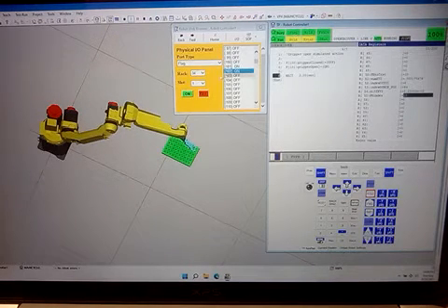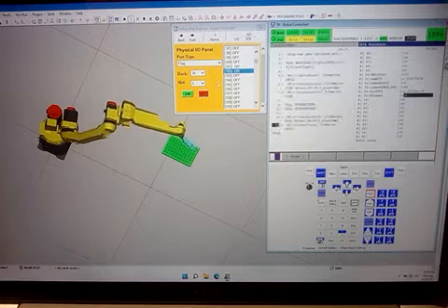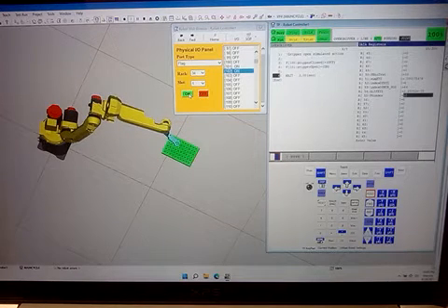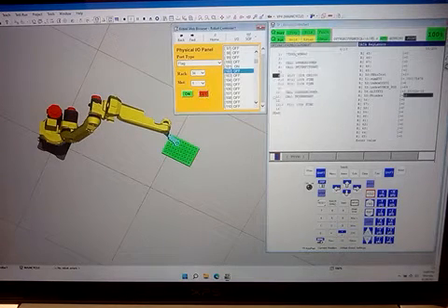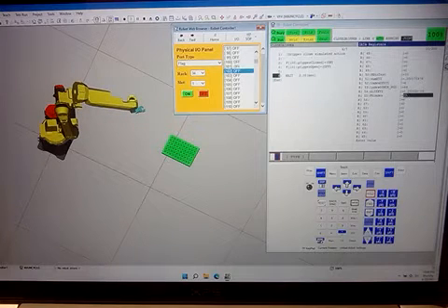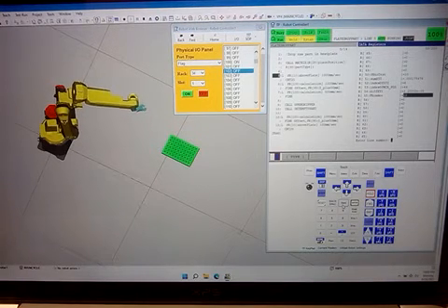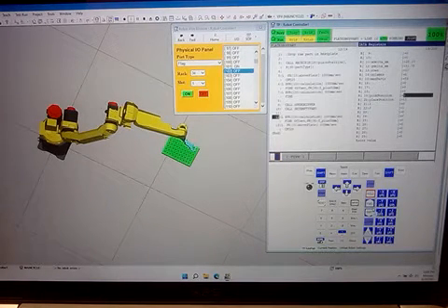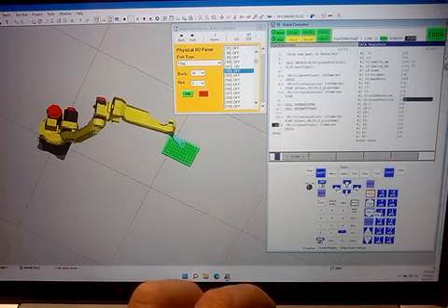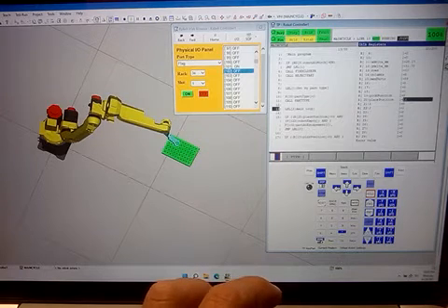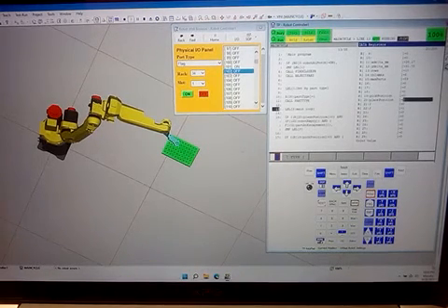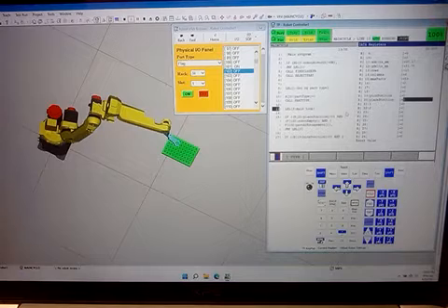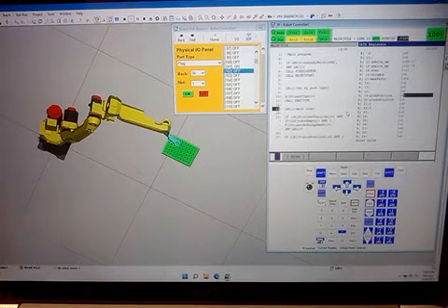Okay, so now let's just stop the picking and dropping into the heat plate. Just gonna stop that. Sensor is gonna go off. I'm gonna go to item 19, and then I'm gonna make that one here 20, which is the position in which to place a part. I'm gonna turn that to 0, meaning it's not gonna place any part. And then I'm gonna change the pick position.